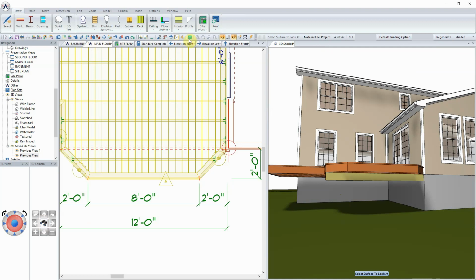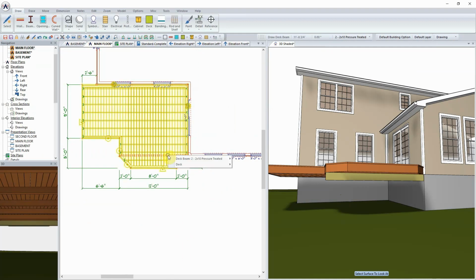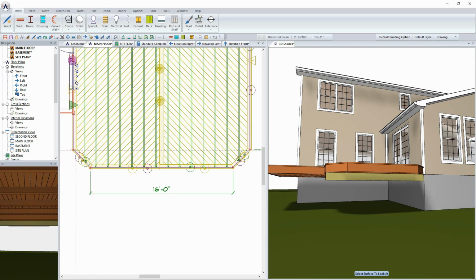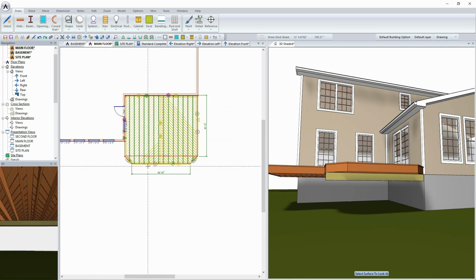And so we could do the same thing in the floor plan. I'll just right click, draw, select, okay, and I'm going to zoom this up, and I'm going to place a beam in here running across like so to support those joists. And so we now have a similar beam running left to right there.